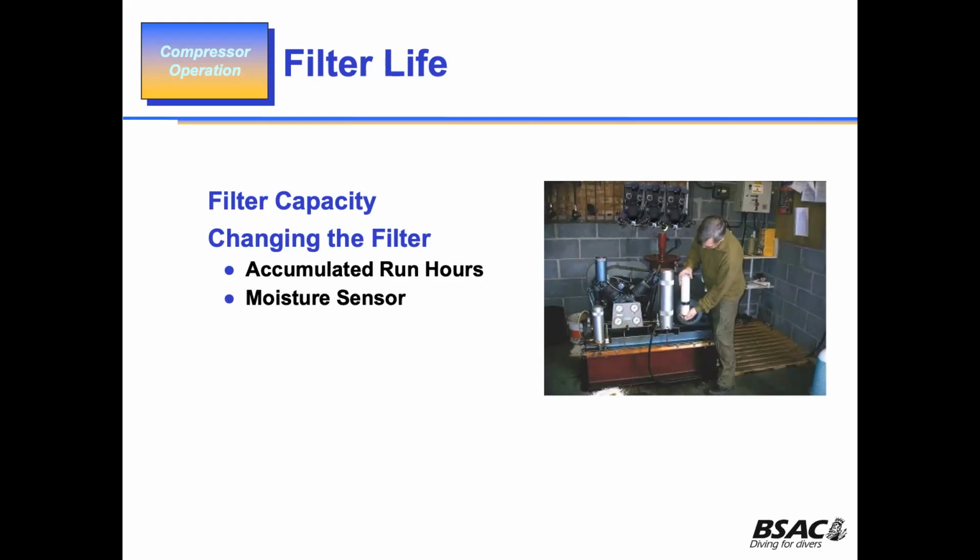Some of them are fitted with moisture sensors. If the moisture sensor shows that the filter is not taking out the moisture to the required degree, then you've got to change that filter.